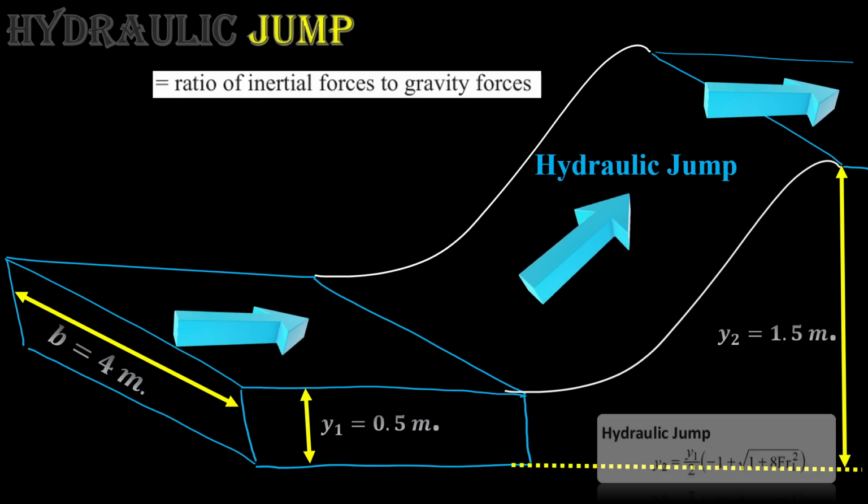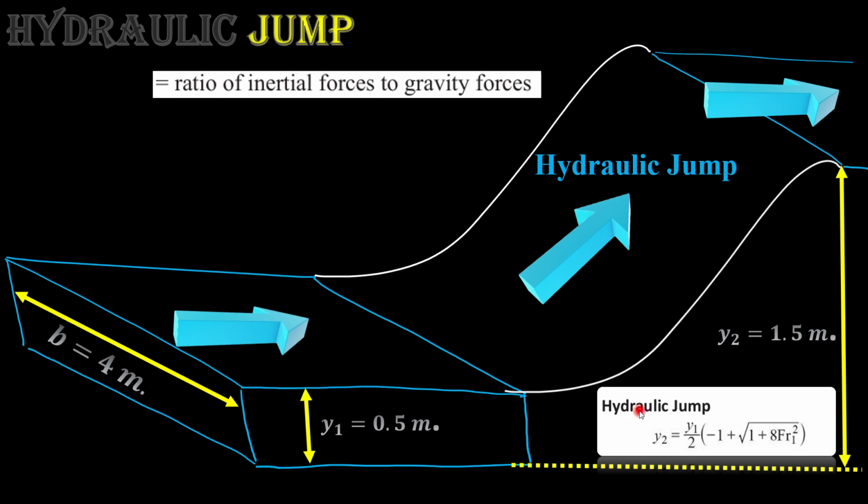So first of all, if you go to any fluid mechanics or hydraulic engineering reference book, or the FE and PE guidelines, you can easily see an equation which refers to hydraulic jump and relates the conjugate depths to each other. So the alternate depths are related to each other with this equation, and then you can see the Froude numbers appear in our equations.